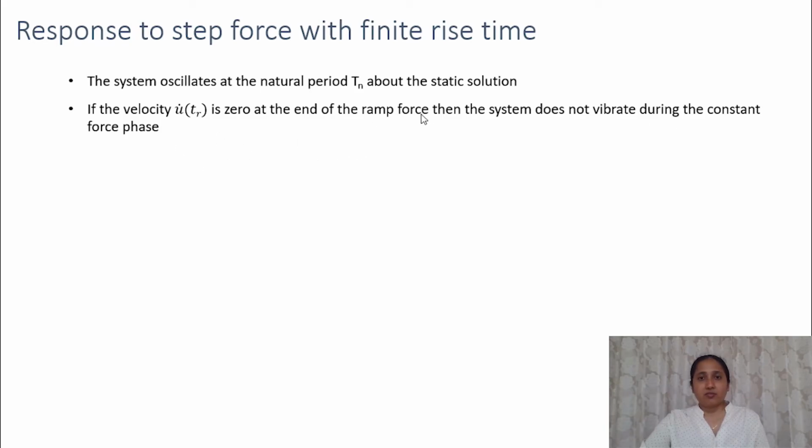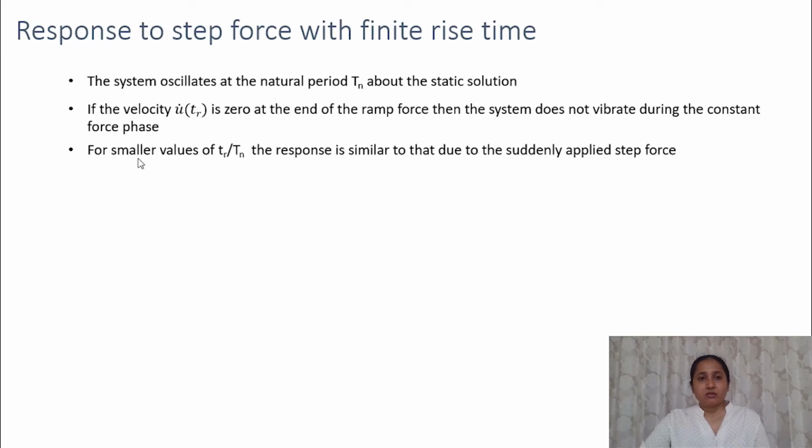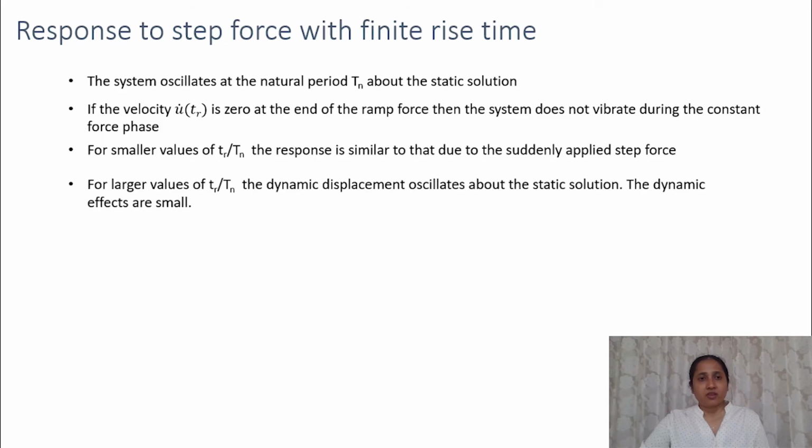So after the ramp force, it will be a constant response. It won't vibrate. For smaller values of Tr by Tn, the response is similar to that due to the suddenly applied step force. So when the rise time is less, the response will be equal to the suddenly applied force.